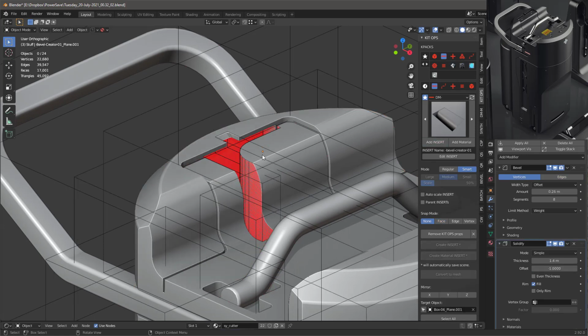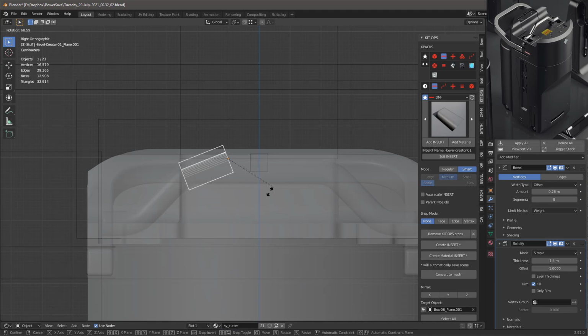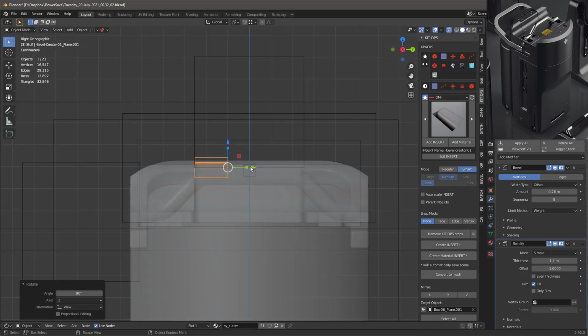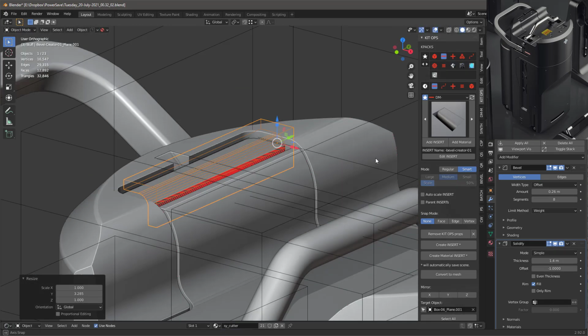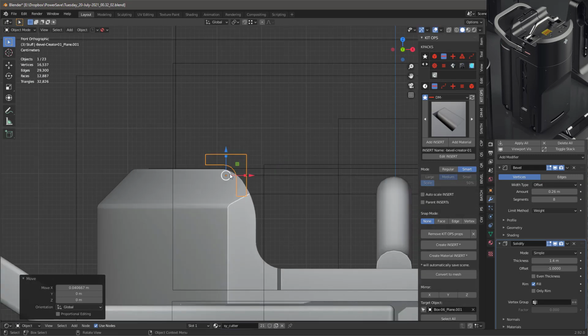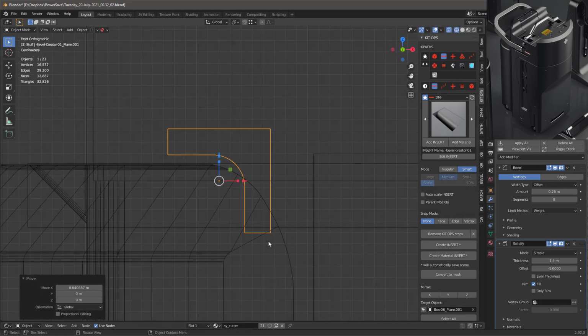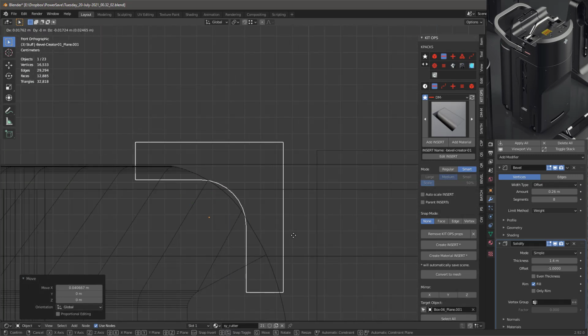And then I've got this little bevel cutter. And so this is kind of cool. What I can do is I can take this and I can rotate it. And I'm trying to find the right position. There it is. So I'm going to rotate it out like this. And I'm going to use this to put a smaller bevel on that side right here. So you can see there's my bevel and there's my cutout right there.